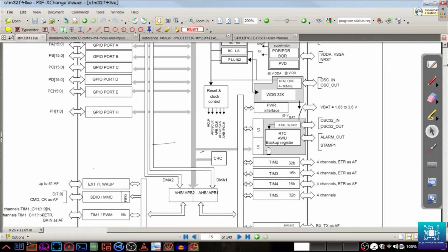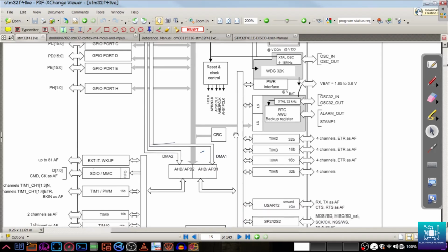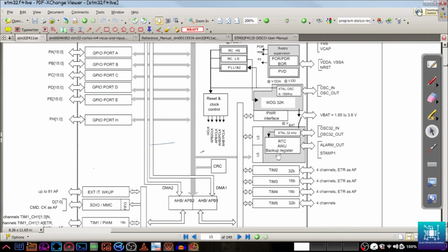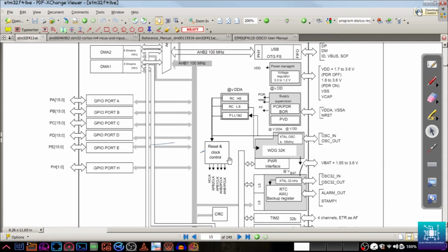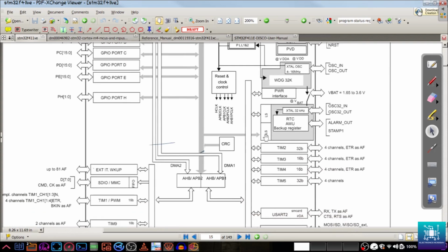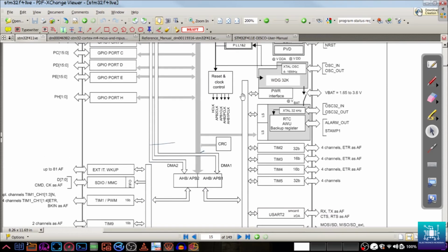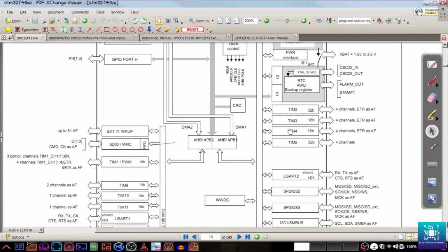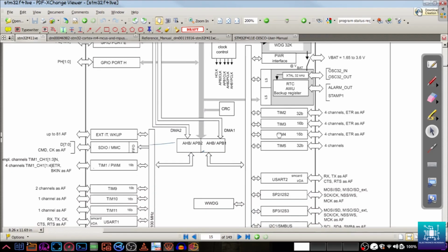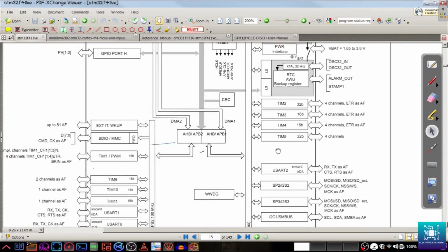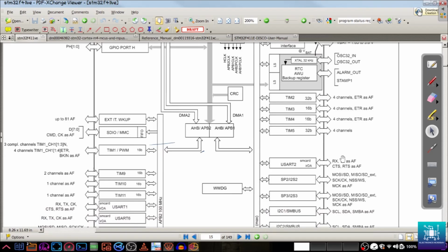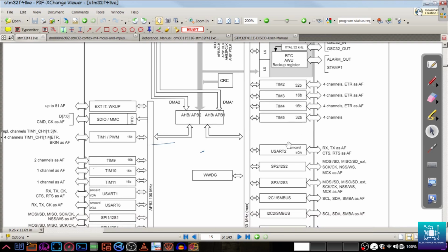We saw that one unit can be connected to multiple buses. For example, as you can see, the AHB1 bus is connected to the LS here. Again, the APB1 bus is also connected to it. So these are just data paths. Data and control is flowing over these buses. That's all. This is just like looking at a map of the controller, how things are laid out. If you consider this as a map, and where the different components reside, it will become easy for you.